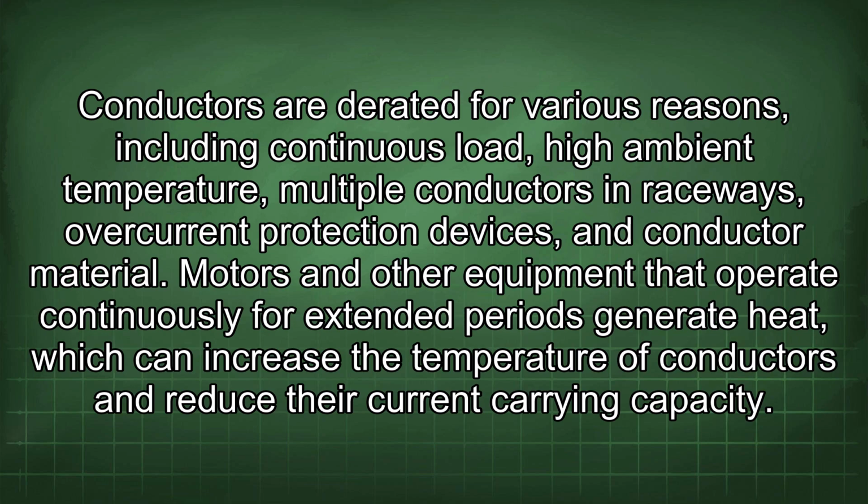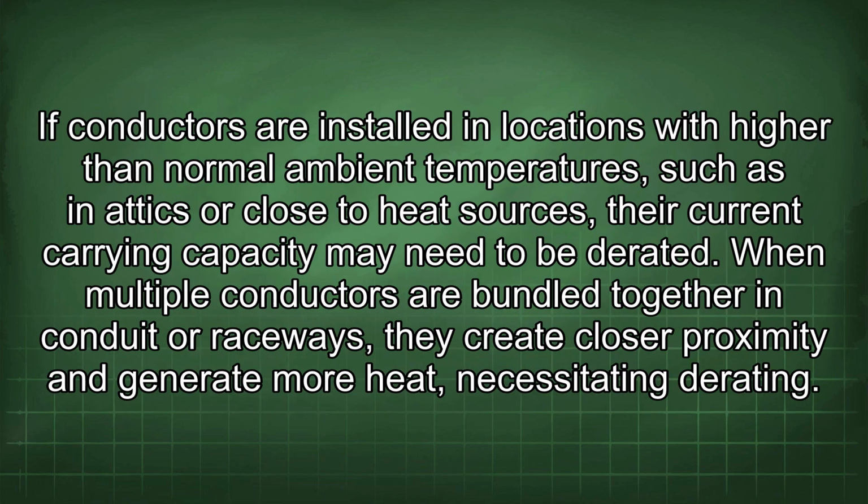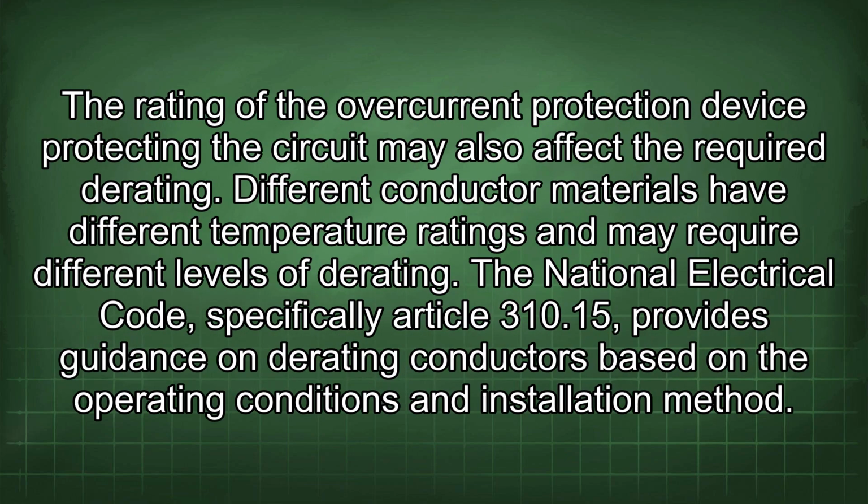conductor material. Motors and other equipment that operate continuously for extended periods generate heat, which can increase the temperature of conductors and reduce their current carrying capacity. If conductors are installed in locations with higher than normal ambient temperatures, such as in attics or close to heat sources, the current carrying capacity may need to be derated. When multiple conductors are bundled together in conduit or raceways, they create closer proximity and generate more heat, necessitating derating. The rating of the overcurrent protection device protecting the circuit may also affect the required derating. Different conductor materials have different temperature ratings and may require different levels of derating.